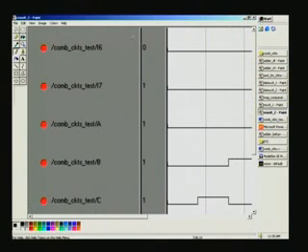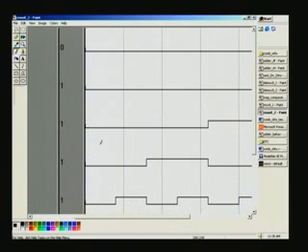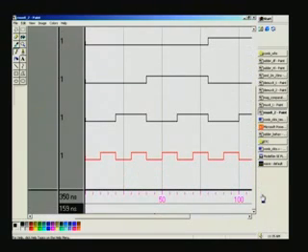Okay, this being a large waveform, it has been split into 2 here, and unfortunately this ABC appears only in the second waveform. But it's not a difficult thing to remember because we go only by the binary progression here. The only thing to remember is that the pulse for a particular input has been created at 10 nanoseconds, and the interval is 20 nanoseconds, something like that, right? And now the time base has been changed in order to accommodate all the possible combinations. That's why the time base is different. So what matters is the actual waveform, whether it is appearing. In fact, you can see the wave here.